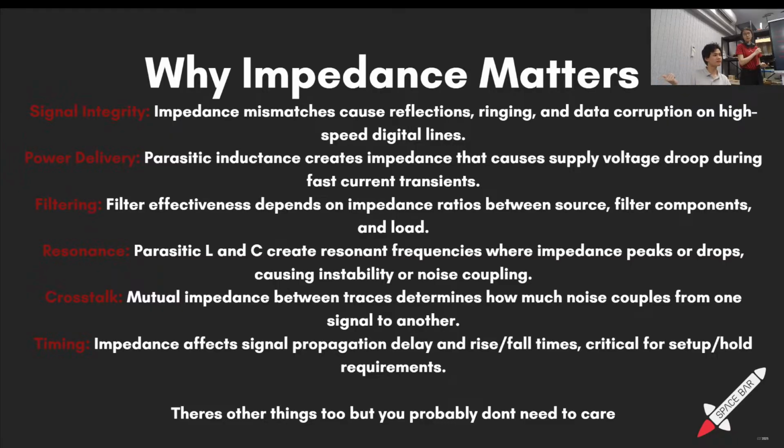Everyone understands why, right? When you have steady state DC voltage, you have constant voltage and constant current. If you have constant current, you have zero rate of change of current, which means there are no inductive effects, which means the inductor doesn't care. It just lets everything through. So the inductor is just a wire now. And you have constant voltage, which means zero rate of change of voltage, which means no current through the capacitor, because current through a capacitor is proportional to rate of change of voltage. So no current through the capacitor means it is an open circuit. The capacitor does not conduct at all.